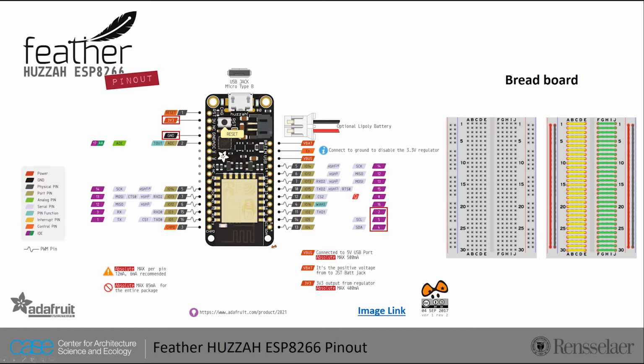The breadboard is the simplest way to construct electronics without having to use a soldering iron. In the breadboard, there are two kinds of strips. The vertical ones are bus strips, which are mainly used for power supply connections. The second one, the horizontal lines, are the terminal strips, which are mainly used for electrical components.